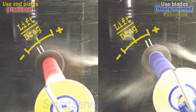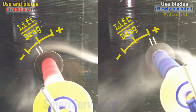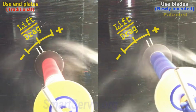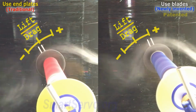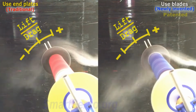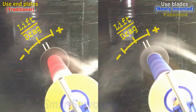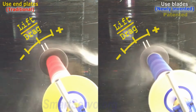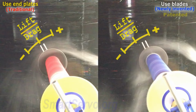The red rotor seems to have a clear boundary from the smoke, and the blue rotor can bring the smoke closer to its surface. Maybe it's because the blades are exhausting the airflow, so the pressure around the blue rotor is lower. This should be the key to reducing drag.